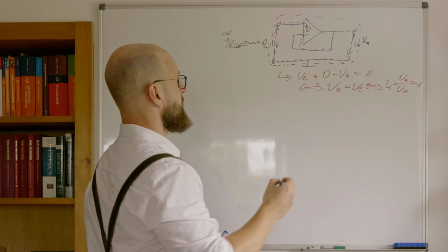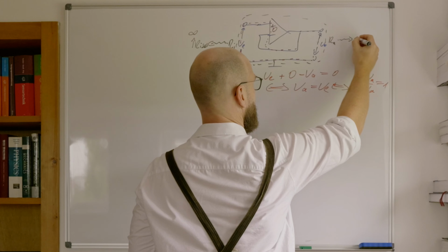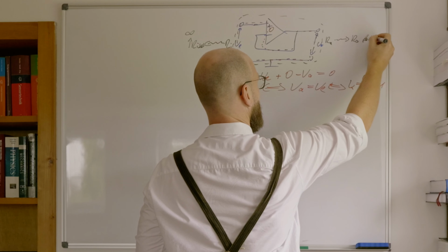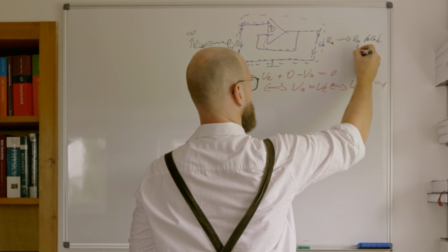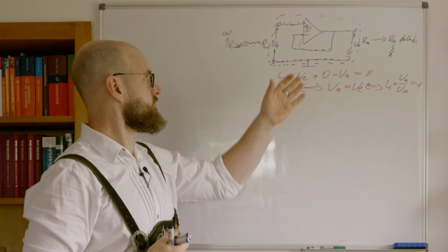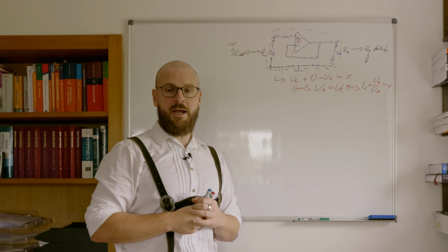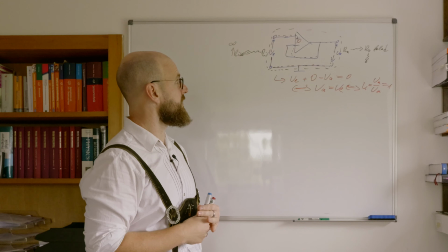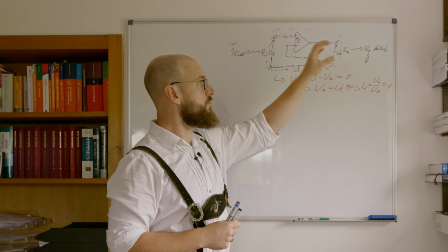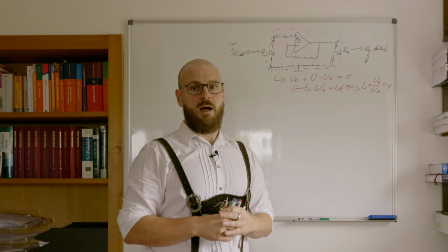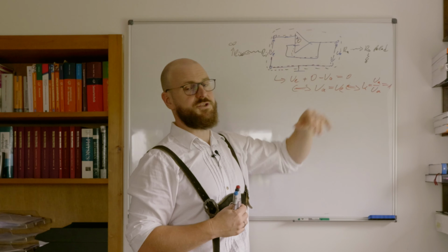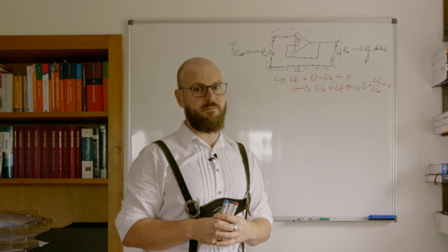On the other side, the output resistance even falls to smaller values, goes to 0 nearly. Again, the same factor, the amplification of the operational amplifier, so we get a really small output resistance, which makes it very easy to measure that voltage UA exactly without any systematic errors.